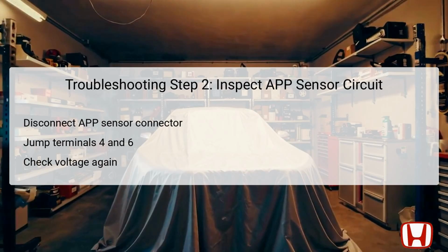In the second troubleshooting step, you will need to inspect the APP sensor circuit itself. Begin by disconnecting the APP sensor 6P connector to gain access to the terminals.